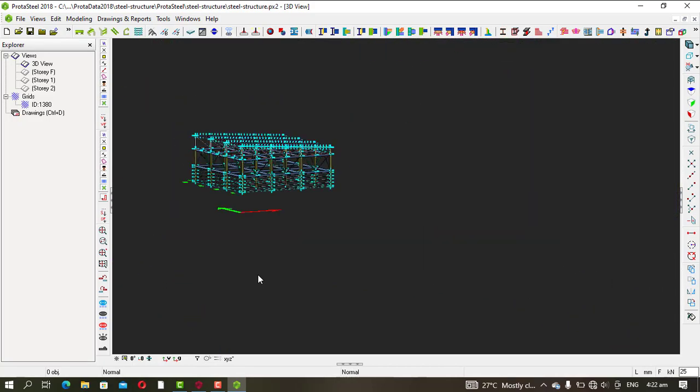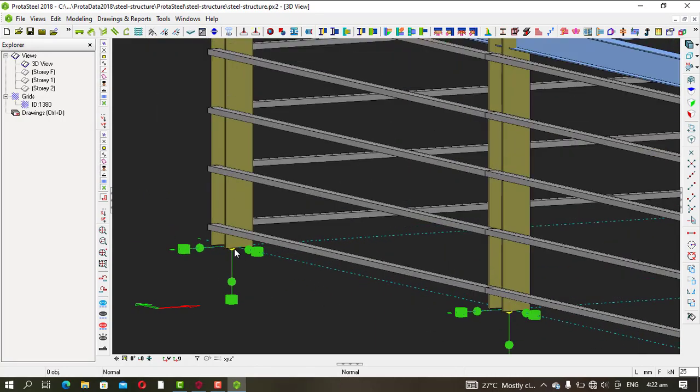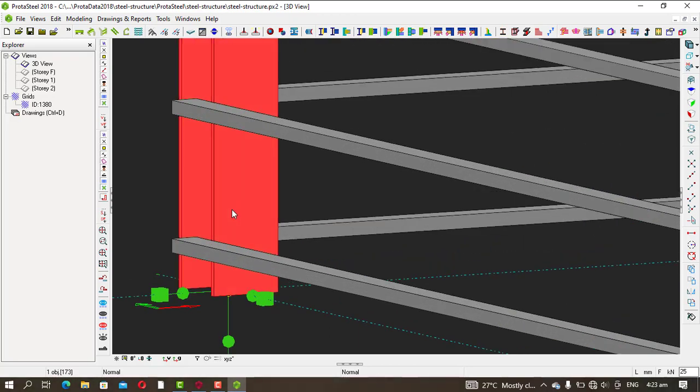we just go into the detailing properly. So I would like to start from the bottom. So we start from the bottom, then we move up. Okay, so this is a steel column, but the steel column will never come directly from the foundation. So we will definitely need a concrete column, that is a concrete column that will be a stud for this steel column.